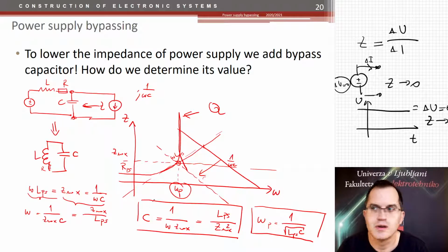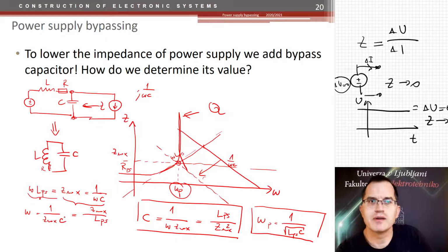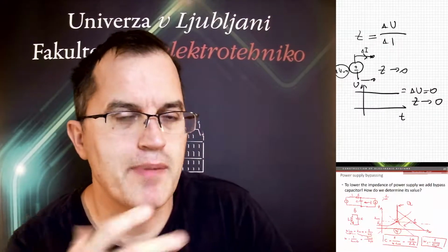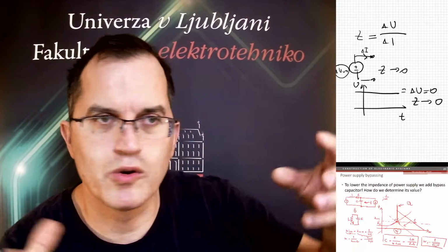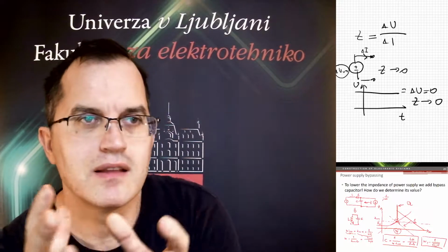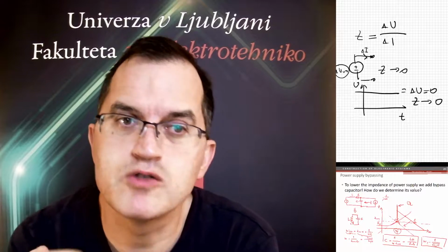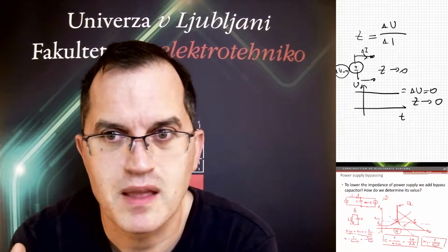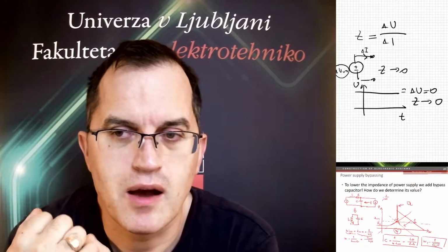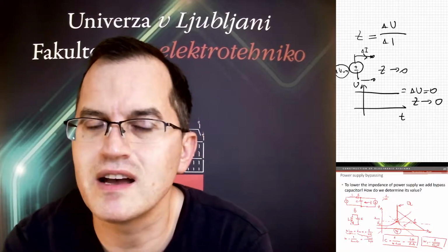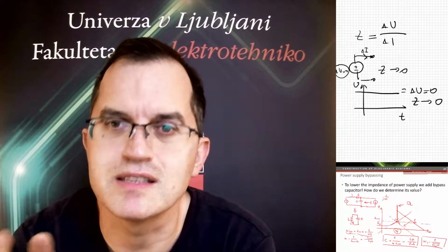Because we could achieve low impedance at all frequencies except at parallel resonance. Doesn't matter what we do, we have this spike here if we use this capacitor. And please remember, all the time, anywhere you look, you have a resonance circuit. A capacitor which connects somewhere would again have some parasitic inductance which would make it a resonance circuit. And the coil has the same.